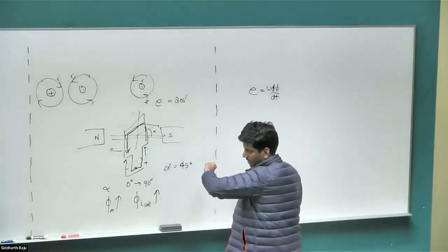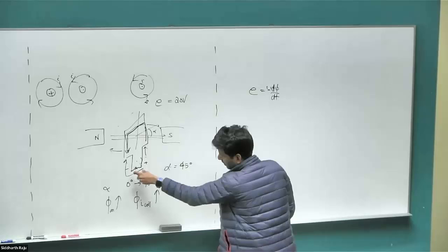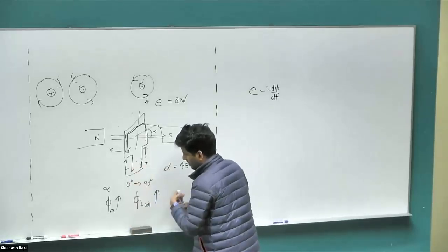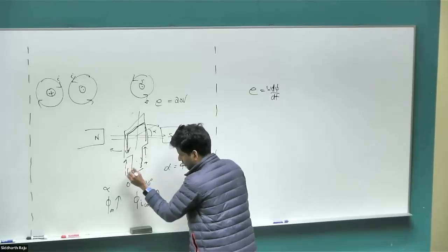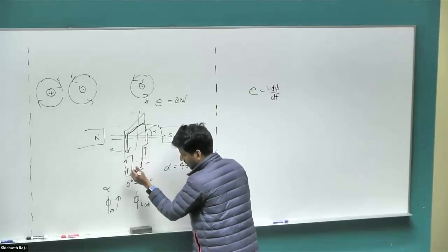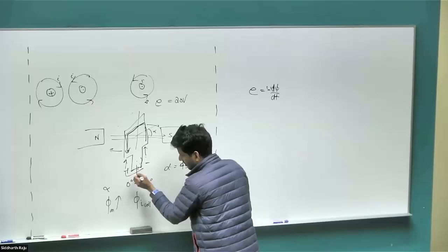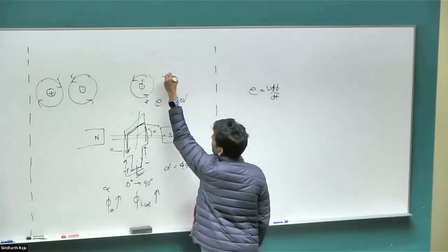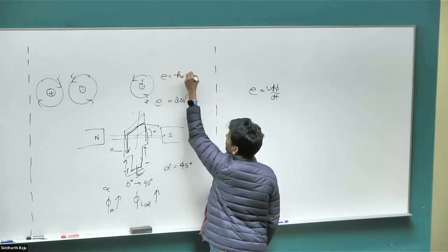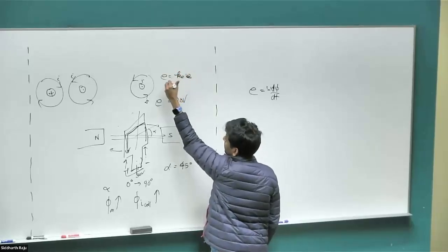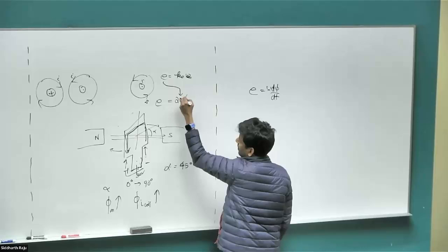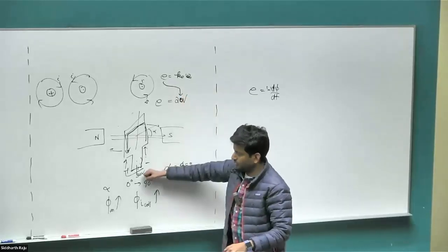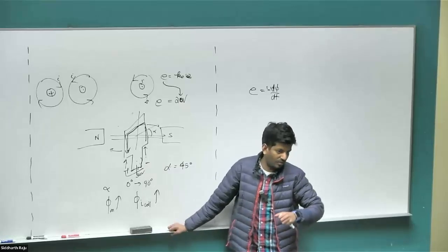So going back to our thing, if I were to apply a DC voltage here, positive voltage, negative voltage. Let's say I apply 30 volts, but this coil is rotating with some speed because I already said it's some Ke times omega. So depending on some speed, the back EMF can be anything. Let's say it's 20 volts. Will this be a problem if the EMF is 20 volts while the voltage that I apply externally is 30 volts?